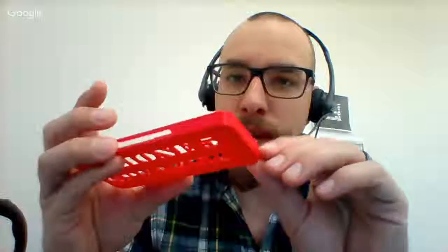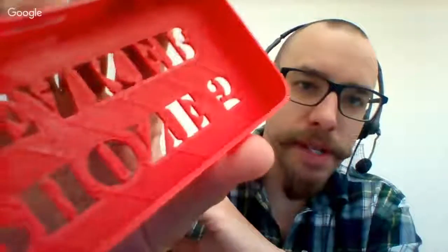So these cases here, I'm not sure if you can see on this grainy video, you can kind of see this little line that's right in here. Well, that's because the phone actually stops right there. And the iPhone 5 has speakers on the bottom. So we just added in an extra 1/4 of an inch. And so it's a sound deflector. And so all you have to do is project up about another 1/4 of an inch and have a cavity there. So that way the sound will actually bounce towards you. I call them little speakers because they work like little speakers. They work very, very well.